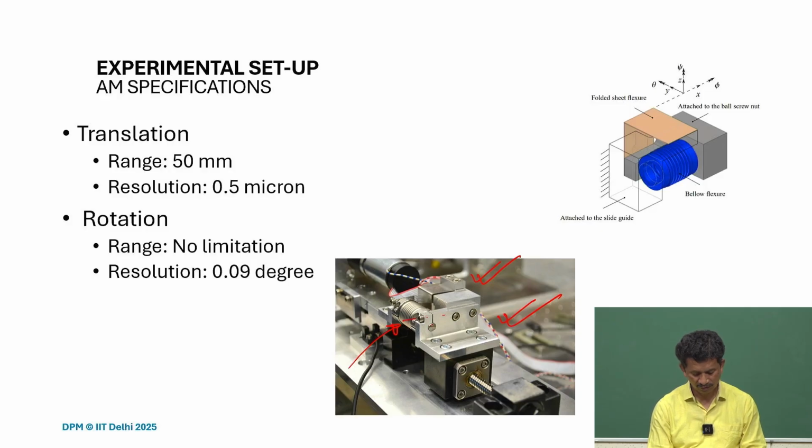One thing you have to also note down, that for assembly we use the rod, and what you can see is to fix it, we make a cut, a slit, so we are using the flexure property to clamp it. We are not clamping directly the pin or the shaft, and there is also how to clamp the sheet flexures in order to avoid a kind of micro slip.